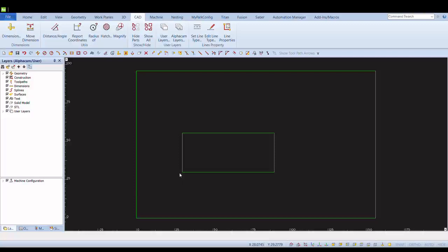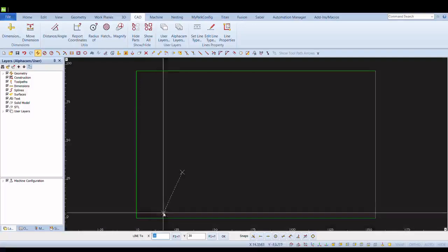We will now show how to draw the second rectangle another way with the line command. To do this, we're going to start by hitting the undo button one time to remove the first rectangle. Now we'll go over to the line command. You'll notice the bottom gray bar is asking for information again. We're going to start at X 30, enter, to Y, and we'll enter 30 again, just like the first corner of the rectangle we started previously.